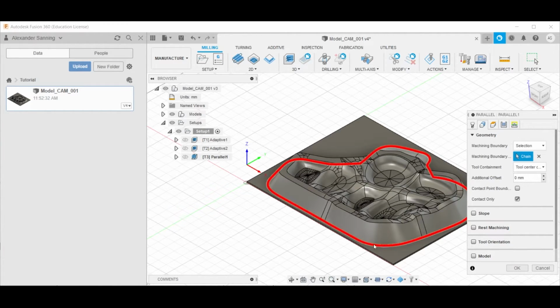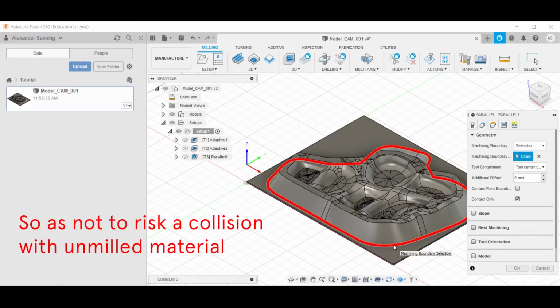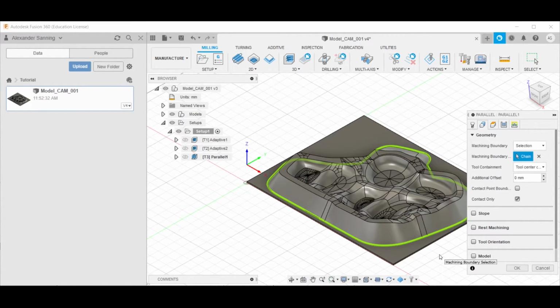This will make sure that the parallel toolpath does not extend beyond the border. We will manually, with the help of other machines in the workshop, cut away the bottom margin and sand the outside of it, so it does not need to go further out. The finishing toolpath does not need to extend beyond the boundary here.